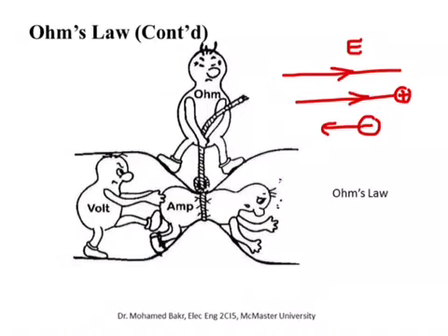these charges are tightly attached to the atoms, so they cannot conduct. Okay, but for good conductors, they are loosely attached to their atoms and they can move around. So in the case of conductors, lots of charges are available for conduction, the conductivity will be relatively high, so sigma will be high. If sigma is high, this means the resistance is low. Okay, and this is for conductors. For insulators, it is the other way around. There aren't many charges available for conduction. Sigma will be low and the resistance will be high.